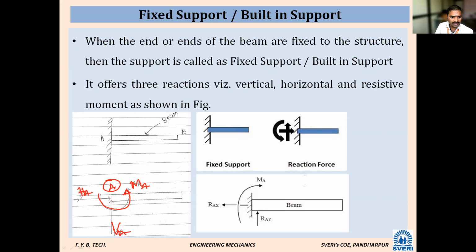Okay, see, in this direction he has taken the arrows towards the point. Here he has taken them away from the point. Here it is taken towards. It depends on you. These are the assumed directions. So by taking these as assumed directions, you have to calculate. If you get a positive answer, then the assumed direction is correct. If your answer is negative, then the assumed direction is wrong, it is reversed.